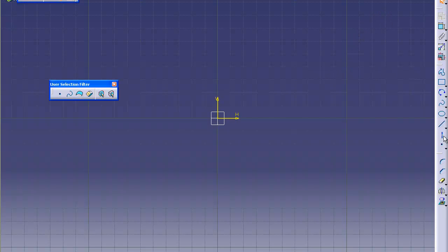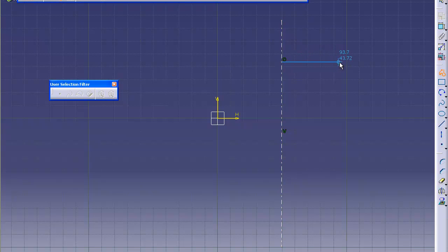and the very first thing we're going to do is create a vertical axis. Doesn't matter where you put it, as long as it's vertical. Then we're going to go into Profile, which is this weird shaped thing here. It's orange now. And we're going to start off with a horizontal line that starts off coincident with the axis. You can see it by that little blue bullseye you've got there. Go horizontal. It really doesn't matter how far. So you're going to constrain other lengths later. Then you go vertically down and horizontal to the left.